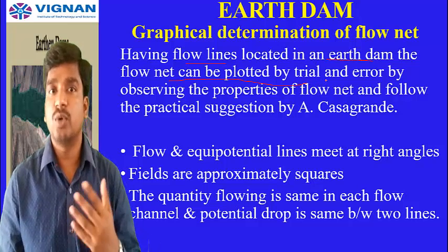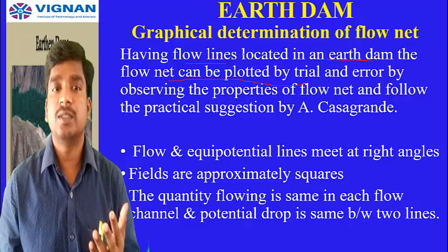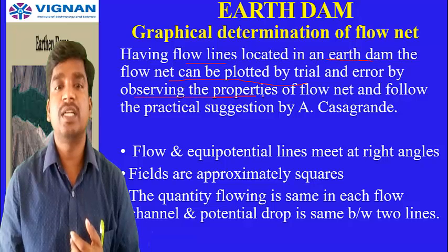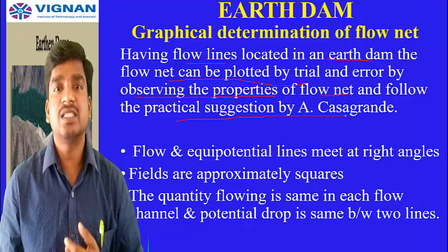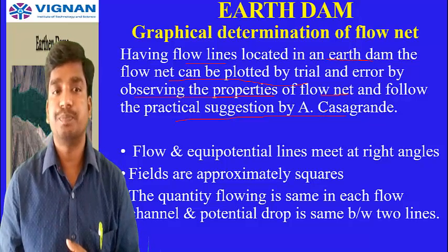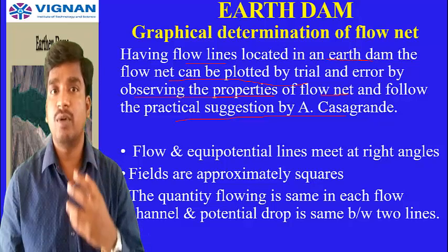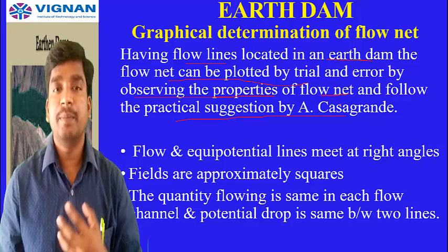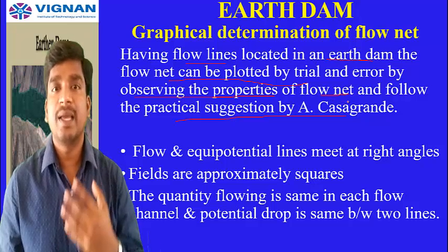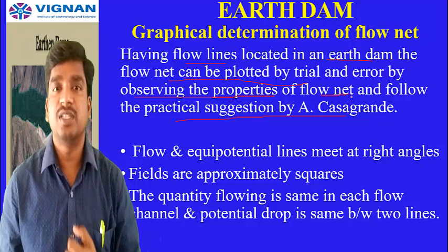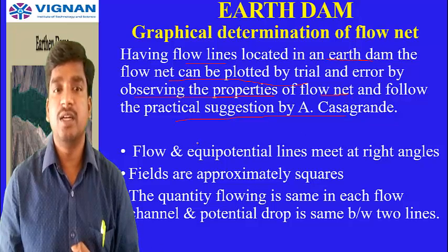So with the help of flow lines, we can draw this earth dam flow net. Observing the properties of flow net and following the practical suggestions given by Casagrande, keeping these two in mind, we can draw the graphical representation of seepage analysis, which is very essential in the case of earth dams. Now let us see what the properties of flow net are.